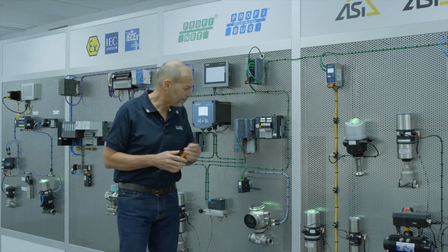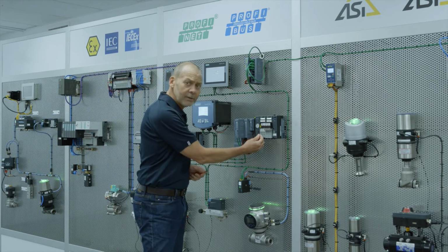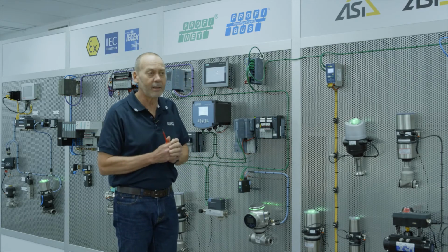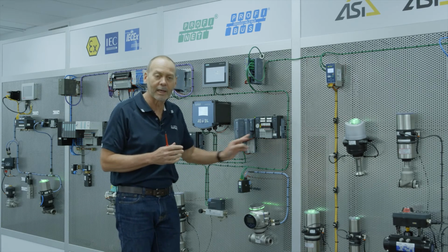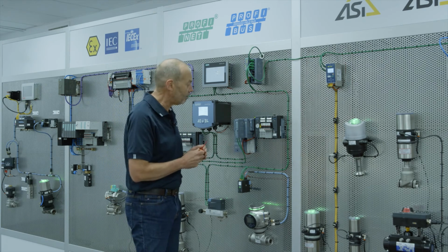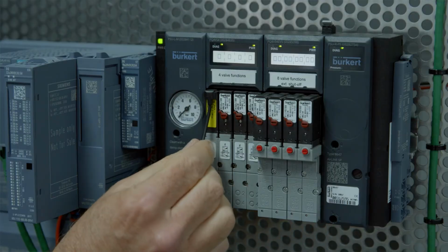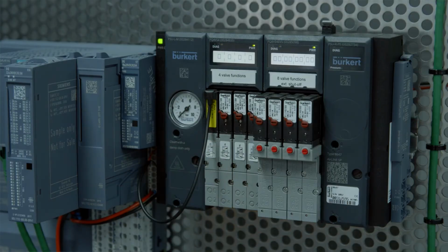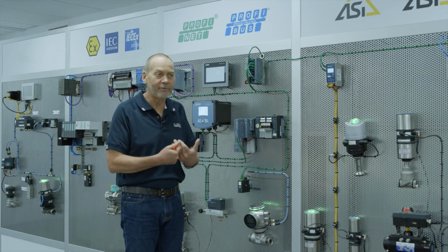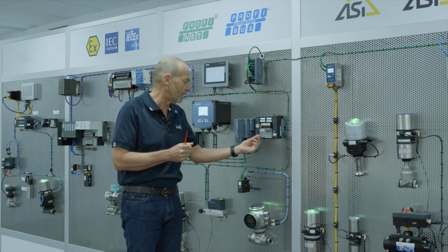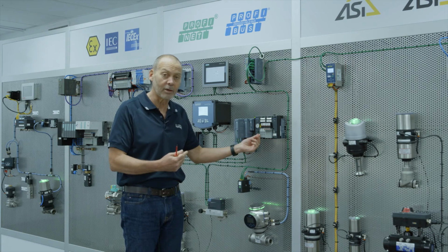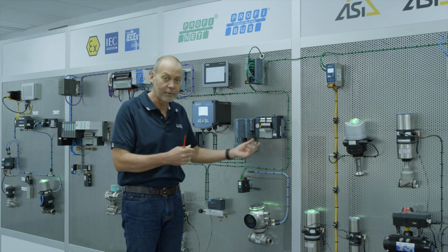Another feature that we offer is the ability to have a safety valve installed as well. These safety valves mount directly into the network, and when they're not overridden by this extra cable here, they are fully running on the network system. However, we have the ability with a safety relay to override that valve and take control of what's happening in the field. So you may have a dangerous situation from moving machinery, or a valve that shouldn't open or shouldn't close because someone's opened a manhole. Therefore, you can override the valve. So in other words, you can have a safety circuit as part of your PROFINET or PROFIBUS circuit.